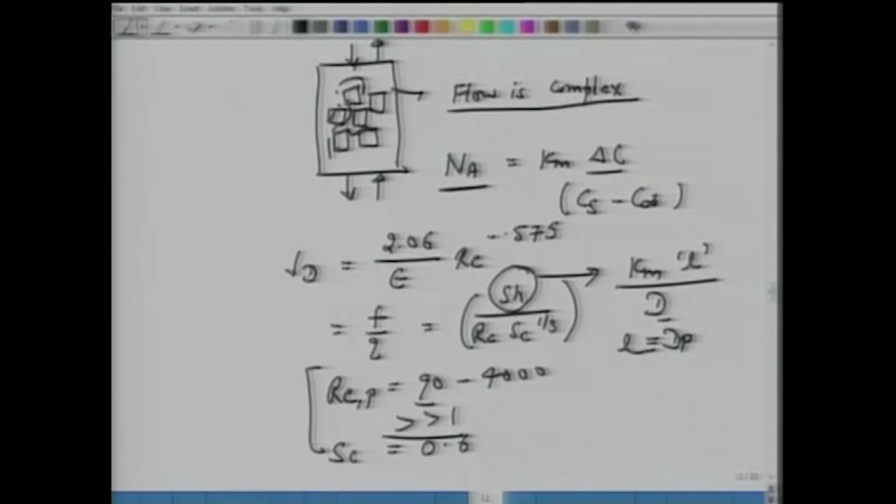So essentially again we have taken 3 examples to show that mass transfer coefficient is an engineering parameter. It has to be estimated, it has to be correlated from the correlations available in the literature. If, for the situation which you are trying to model or which you want to study, the mass transfer coefficient is not given, then one has to obtain it experimentally.